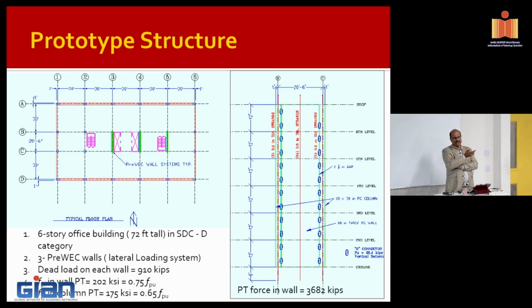So when you do a quasi-static test, like I will be doing some testing in the lab, I will say earthquake testing. People walk in and say, you said earthquake, nothing is shaking. Because I was quantifying how much static hysteresis damping I'm getting. If you do it under actual velocity, then both dampings come in, so you need to separate which one is which. The quasi-static test itself has some value in giving you how much damping it has. But we need to be careful that it can also alter the other damping, because it alters the velocity.